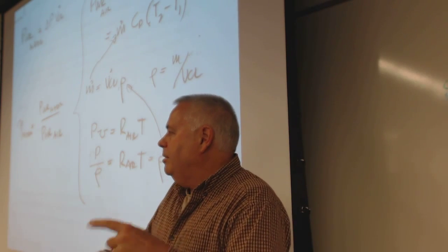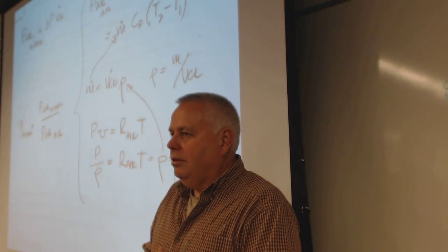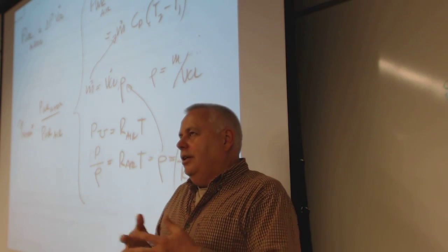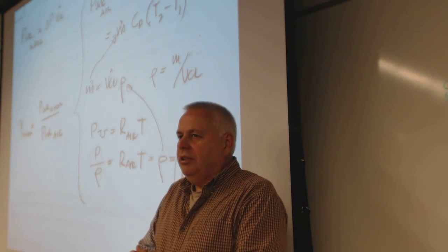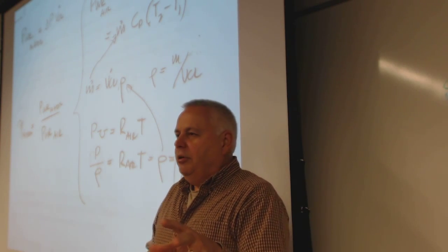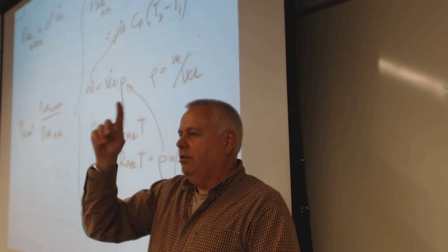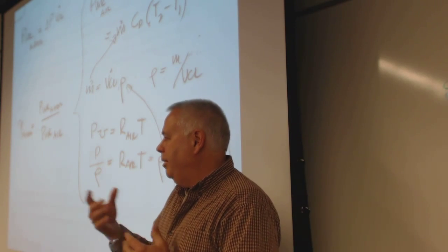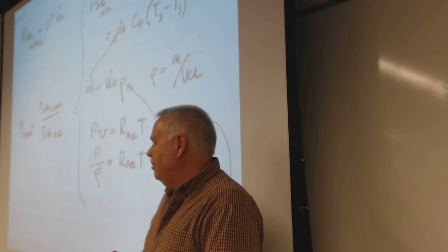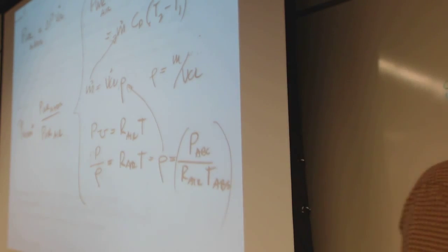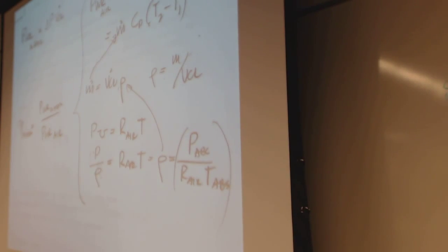If you're pumping something and you also need to condense, like at the biodiesel plant, they don't do this there, but they have to evaporate methanol to recover it. Well, if you're pumping with an air motor, you could use the exhaust to run through the condenser and help condense the methanol, or what have you. So sometimes I can imagine cases where this would be useful.